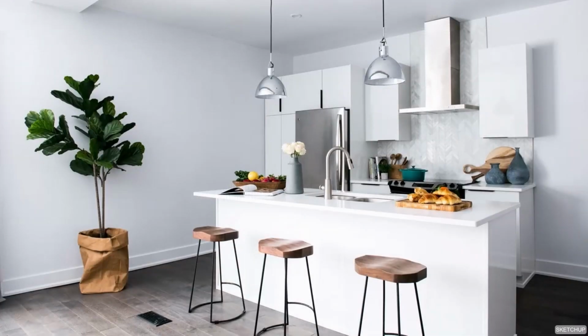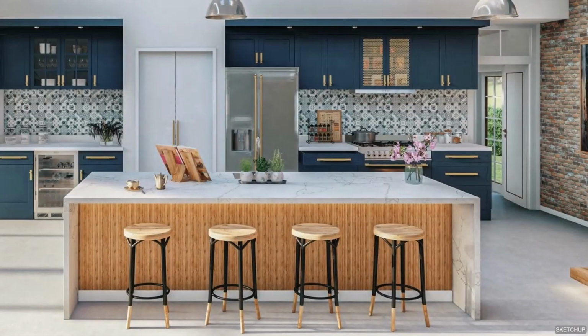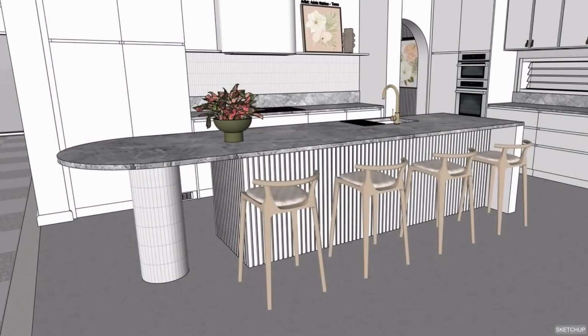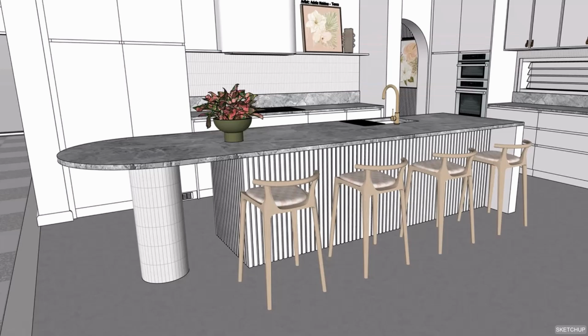If you're planning on incorporating 3 island chairs, a total length between 2000 to 2200mm is ideal. If you need to accommodate 4 bar stools, 2400 to 2600mm is a great size. For larger homes and kitchens, a longer 3 to 4 meter or even more island bench creates a fabulous feature.